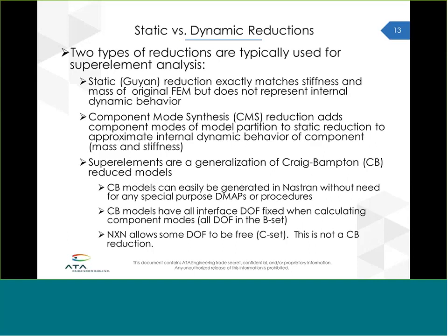So the way that it's done in Nastran, superelements are really based on the Craig-Bampton method of component mode synthesis. So you don't need any special DMAP alters or anything like that. It's just the built-in method.